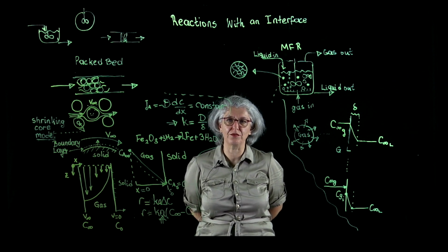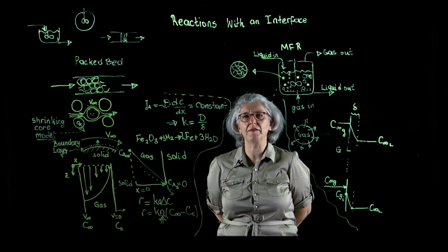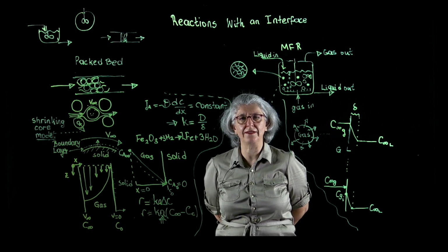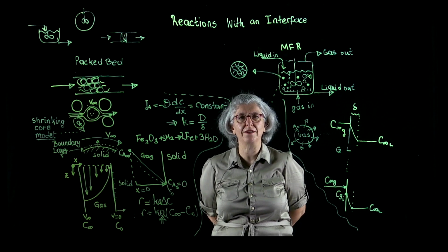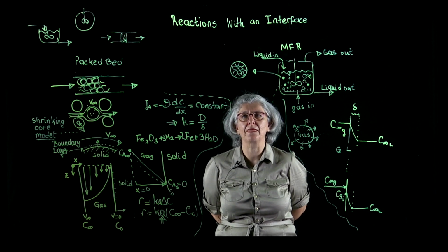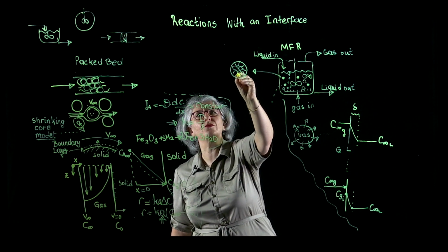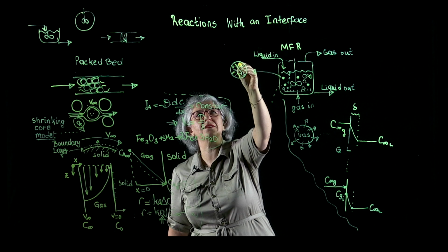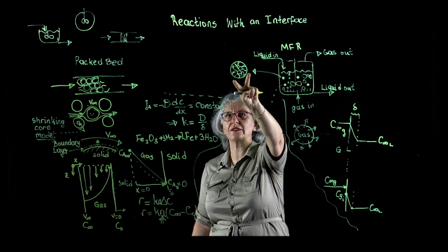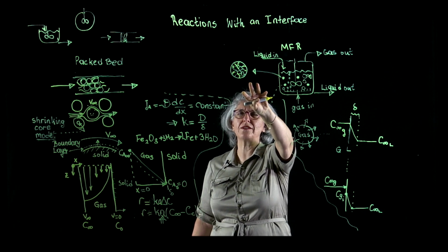The solid catalyst in this multiphase medium of gas, liquid, solid domain is a porous material. It has to be porous because we need to make sure that we have the maximum available number of active sites, and the only way that we can ensure this is to have a porous structure onto which we load the catalysts. Now, the porosity in that catalyst I represented through the tortuous paths, the lines. Now we are going to start our discussion from this spherical geometry with a tortuous geometry within itself.